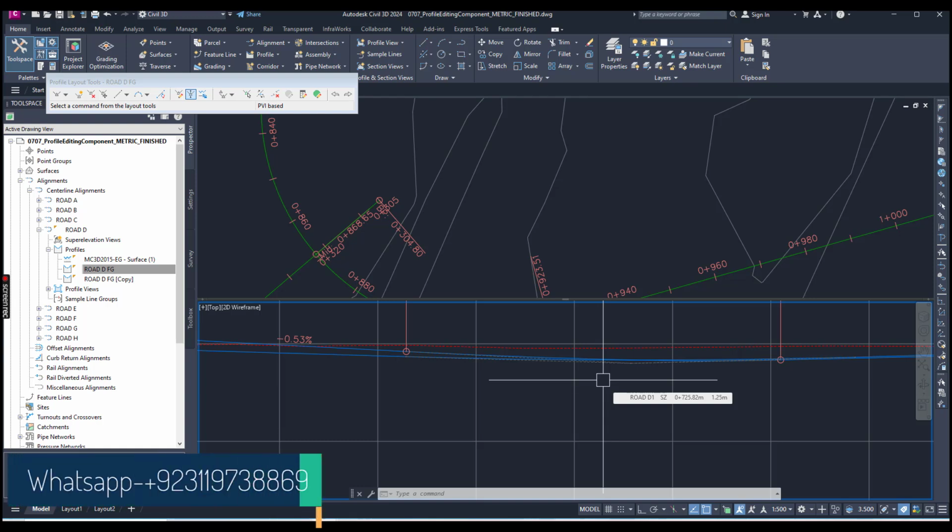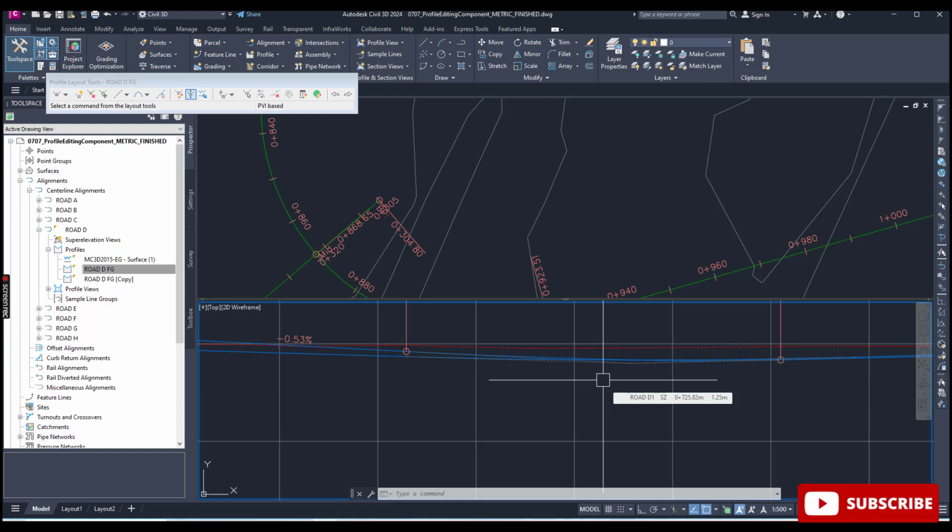If you did not dismiss the notification and then saved and closed the drawing, if the drawing is opened later, the notification would no longer be there. If you are used to the profiles not being locked with the horizontal alignment, you will notice changes, namely with profile locking on. You will notice that even if the alignment changes its length as reflected in the plan and profile view, the design profile ends are tied to the new beginning and end station on the alignment, and the properties for the sub-entities in between are modified to accommodate these changes.